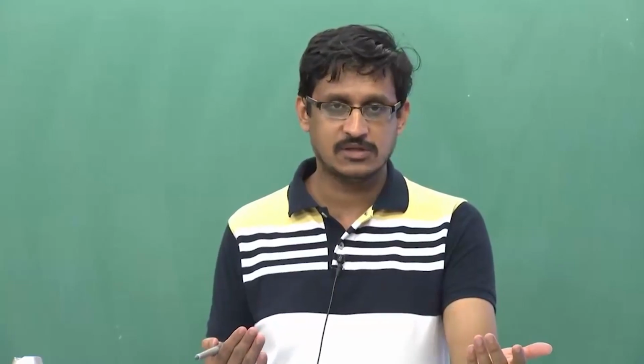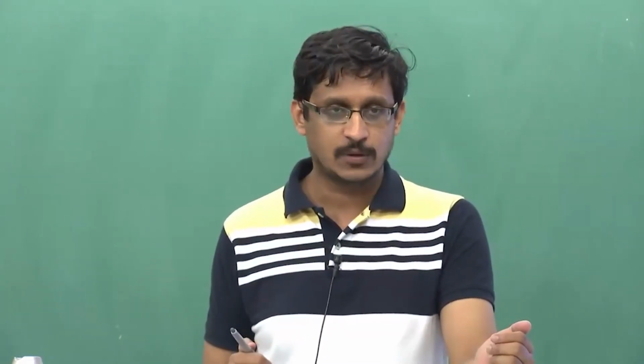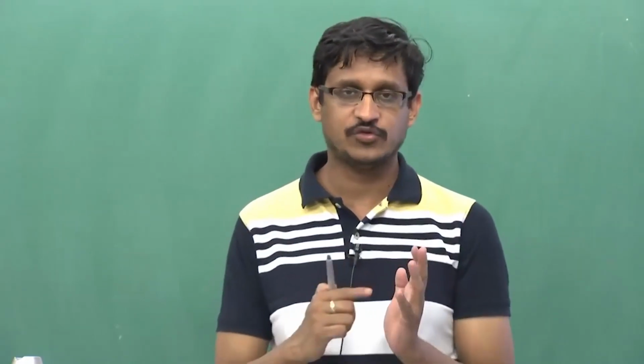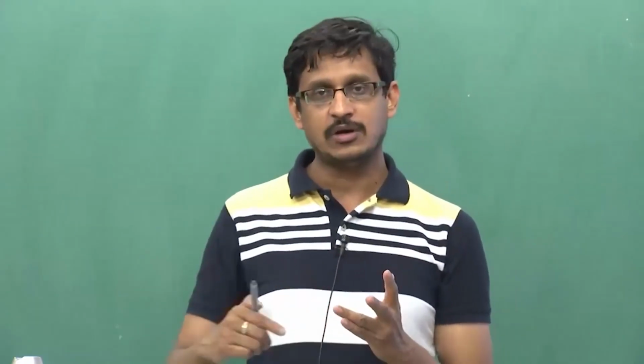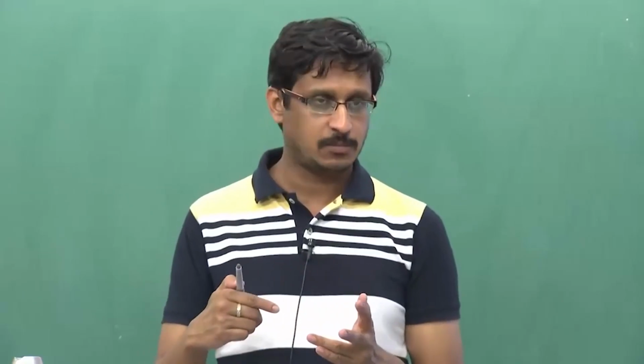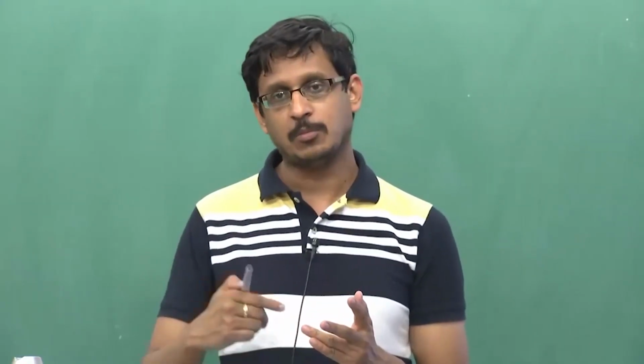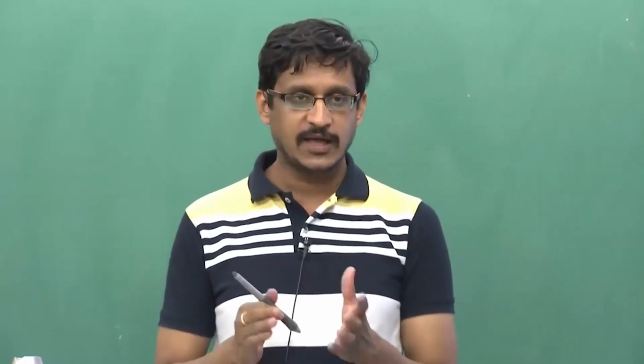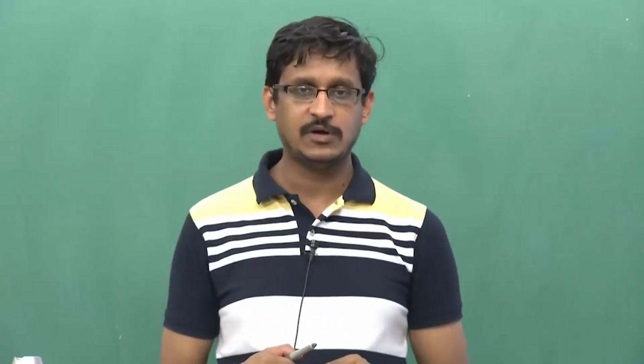With respect to z, you have e to the power minus j beta z. This is the propagating solution that we are considering inside the fiber. Therefore, in the fiber you want oscillatory modes with respect to r, an angular distribution determined by e to the power j nu phi, as well as propagating terms in the z direction, which is e to the power minus j beta z. There is a constant A which is multiplying this electric field.